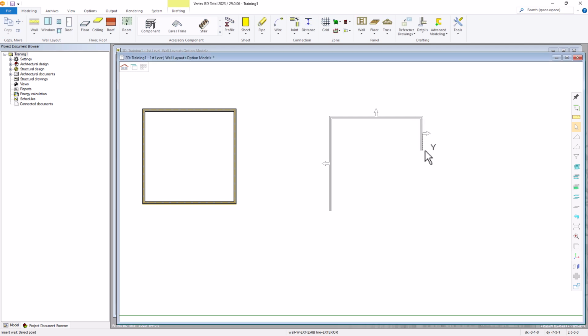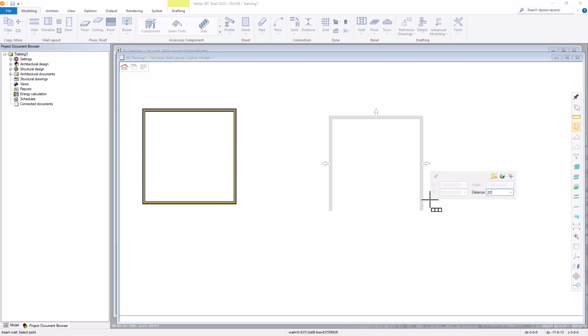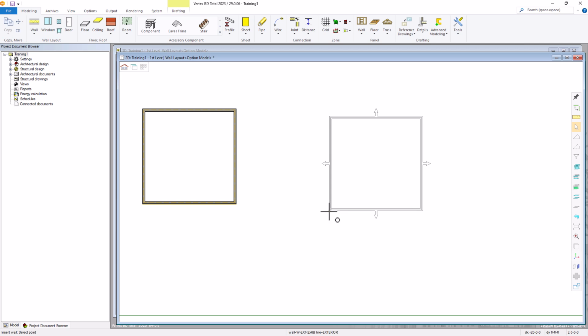We can do the same thing. You can just hit the I key, so we know that the y-axis is the letter I. Pull it down in the direction that we want to go. In this case, it's towards the bottom. Type in 20 feet, and you see that it populates a distance field. Hit return. Now we'll just pick our start point. So that's how you use your constraints.